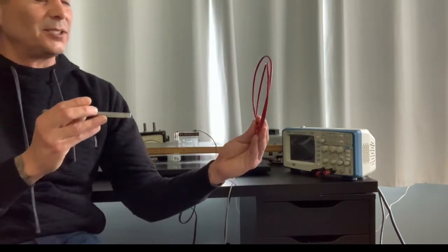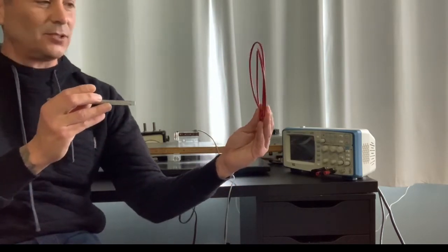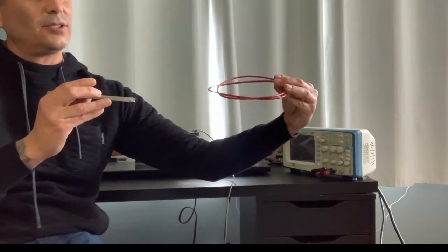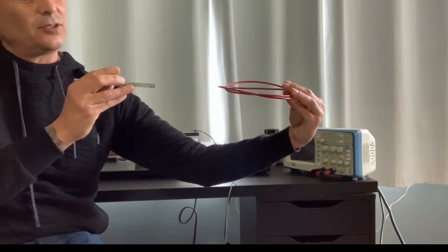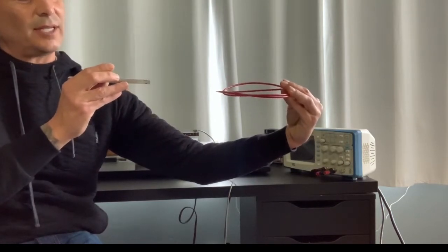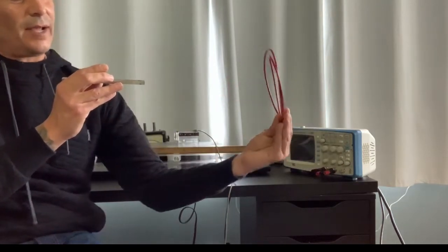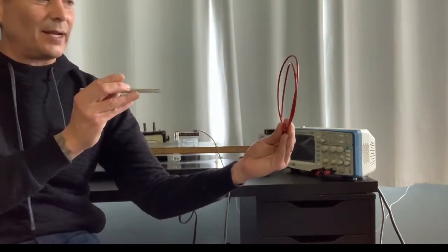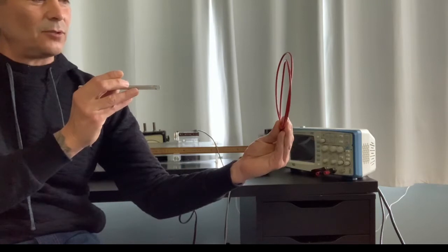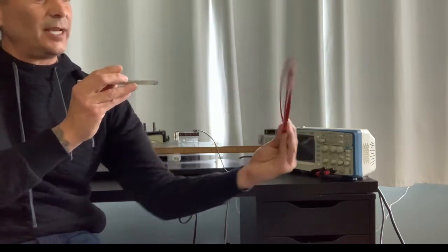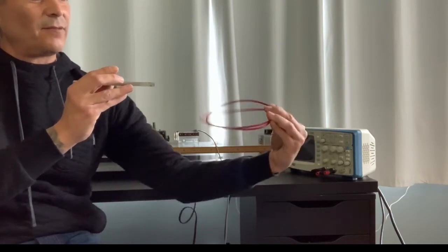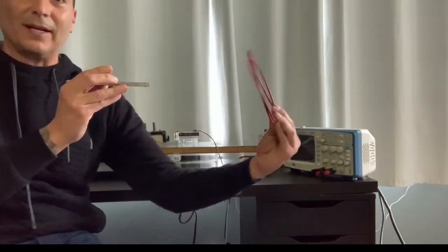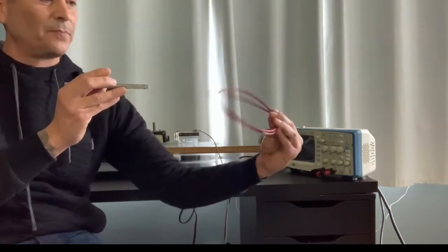And the last situation would be the orientation of these loops. If these loops are situated this way, you can see that there is no magnetic flux going through the center of these loops. If I have it like this, some maximum amount of magnetic flux is going through the loop. So if I constantly changed it, the magnetic flux going through the loop is constantly changing, and in effect, there'd be a current through the loops.